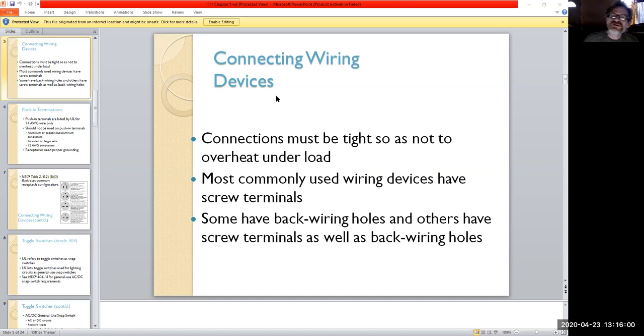But you always want to make sure of that. I always give everything a really good tug test after I've secured it down. You screw down the wire and it looks good, but not all the time. Sometimes a screw gets cross-threaded and feels like it went down tight, but you still have a little bit of an air gap between the screw head and the wrap of the wire, the little copper loop. You'll start getting arc flashes on that little bad boy, and it'll crank out an amazing amount of heat. It's just crazy.